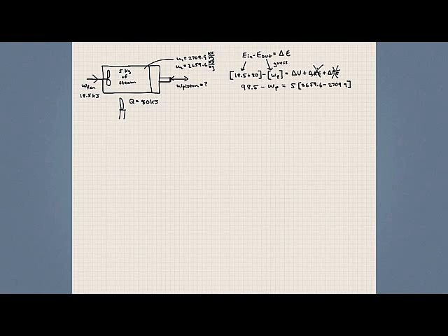So what I've written is mass times U2 minus U1. So solving this, we would get a positive 350 kilojoules. The positive indicates that it's work out, or the piston moves to the right. Okay?